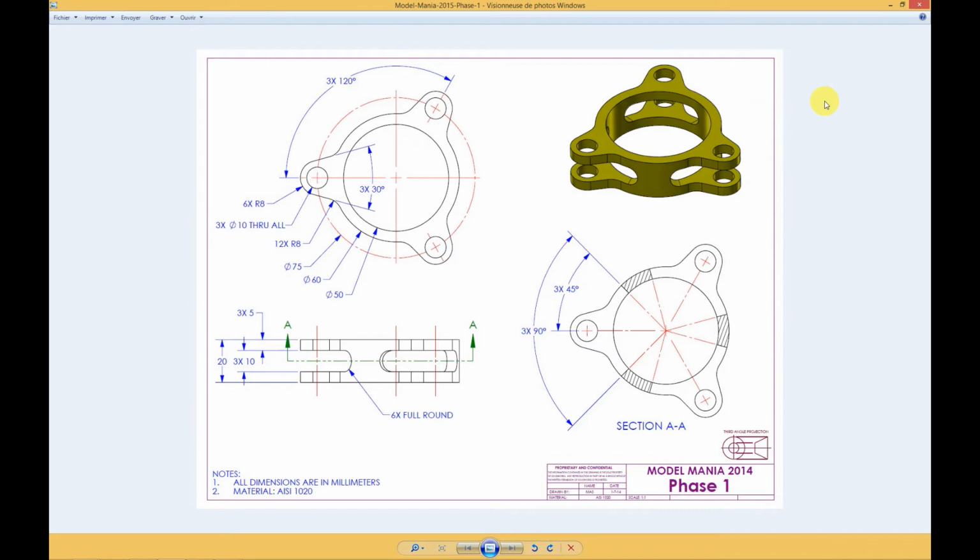For this tutorial, I've decided to create a geometry from the drawing you are seeing on your screen. If you are interested, you can find in the description below the video a link to this image so that you can try it on your own. The key point to keep in mind is that this drawing describes the 3D representation of our part. But in the case of our tutorial, we aim at modelizing a 2D shell finite element model. So basically, we need to extract the mid-surface of this 3D representation. And that's the model I've created using Salome.